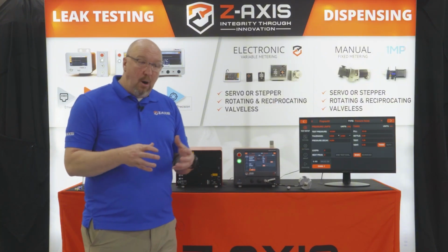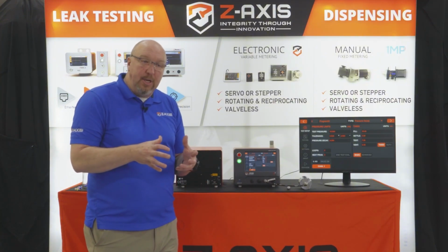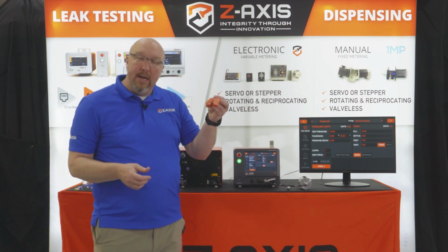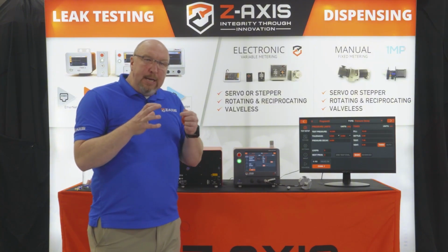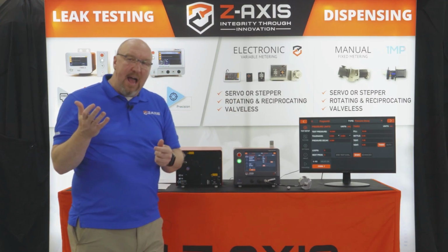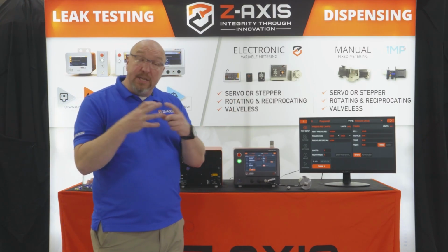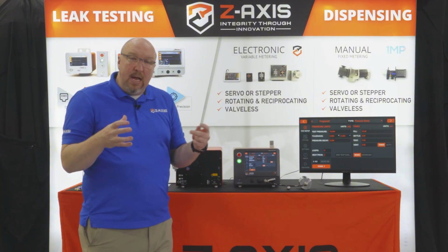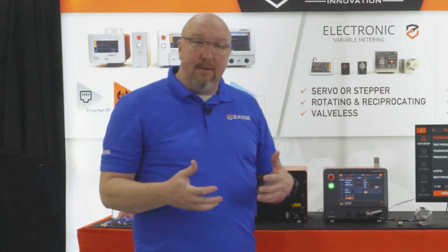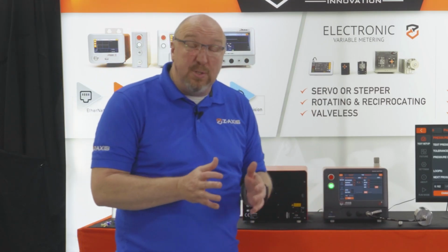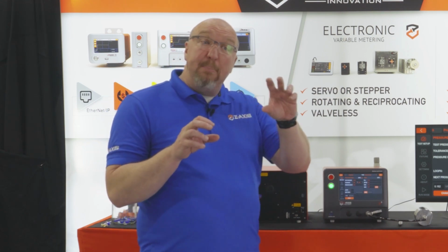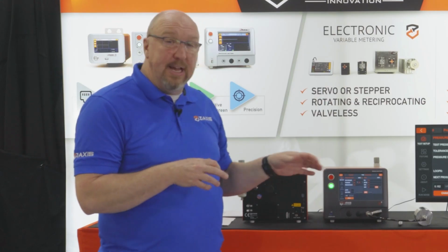So the more we test a part, if the part had some compliance or some stretch, the more that compliance is going to stay. It's the same idea as the party balloon, right? The first time you blow up that balloon, you about blow your eardrums out because it's very hard to get that balloon to go. Well, if I let the air out of it and blow it up a second time, it's much easier because the compliance is already there. So it wants to get to its final shape faster. The same can happen in leak testing. If we're using 1 sample part or a few sample parts, because that's all we have, what we'll tend to see is the results will just get better and better naturally on their own because of things like compliance.